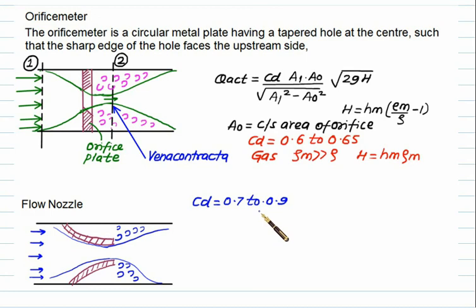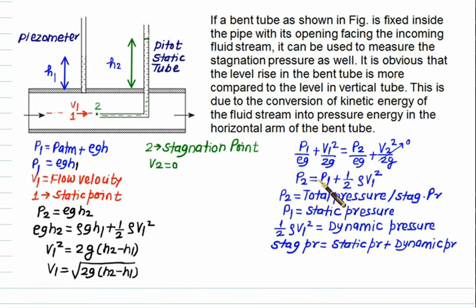If you are interested to know the local velocity, in that case you can use the 90-degree bend pipe, which is also called the pitot static tube. To measure the pressure, here we are using a piezometer. So we'll consider here two sections, section 1 and 2. Initially this tube is filled with water. Velocity equal to V1 at section 1. Water will enter here and water will rise here. Depending upon its energy, it will attain the maximum height equal to h2.